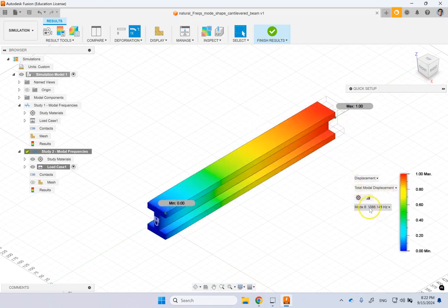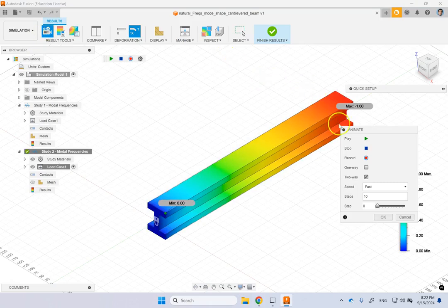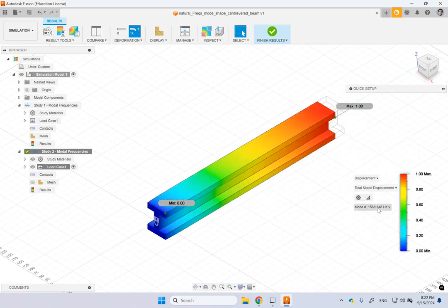This last one is not a deflection or twisting. This is the change in the length. This is basically the extension and the shrinkage, or the longitudinal vibration that you can see here, and the frequency is very high. Okay, so this is a simple vibration modal analysis. Of course, this is not forced vibration or anything. This is just pure free vibrations.